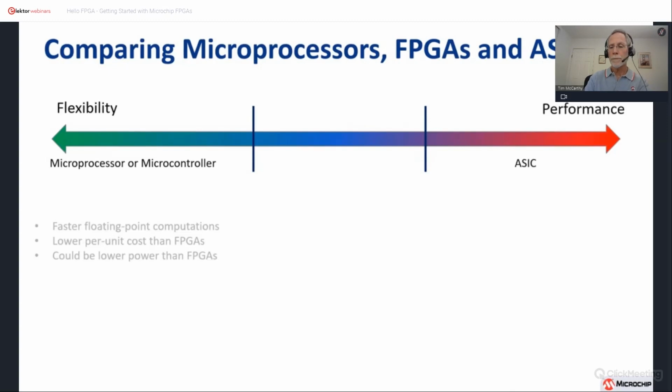An ASIC, or application-specific integrated circuit, is a microchip designed for a specific application. ASICs are generally implemented as gate arrays, standard cell, or full custom designs. In gate arrays, the transistors and other active devices are predefined. The final metallization layer connects the transistors to implement the specific design. In standard cell designs, the mask is a custom design, but the silicon is made up from library components. This gives a high degree of design flexibility, provided that the standard library functions meet the design requirements.